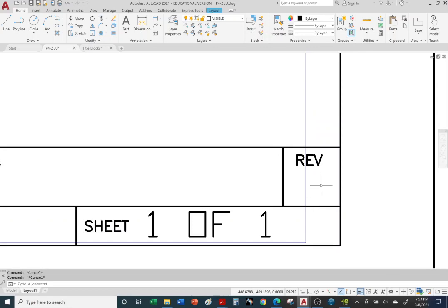Typically when you start with a brand new drawing and it's completely dimensioned, notes, you got everything on it, you'll start with the new revision, and some companies like to use a little dash like a minus sign, or NC, no change, meaning it's the original, right? The original one. Instead of using OG, they use NC, no change. Okay, and some companies will start with the letter A. You go in alphabetical order. So this can be revision A.